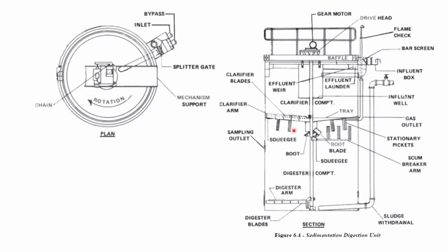Okay, and as I mentioned, we also have a digester arm. Well, I didn't mention this. We have a digester arm that's also making sure that sludge blanket is uniform. The sludge blanket is being decomposed, and as we need to evacuate it, we'll take it off from the bottom of the sludge blanket and send it to a drying bed. That's it in a nutshell.